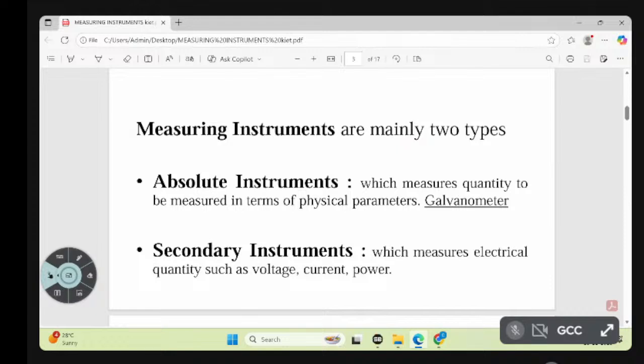Now suppose there is an energy meter. You have an energy meter in your house, right? What do you call it? That is an integrating instrument. What will it do? It will increase the value: 1 unit, 2 units, 3 units, 100, 1000, so everything keeps adding up. Integrating means adding. The energy meter is integrating. Indicating means whenever you switch on, it is showing. Recording means the value is noted down every 1 minute.